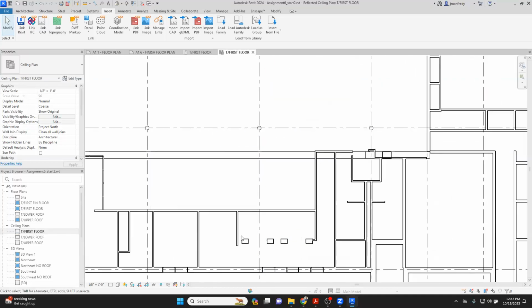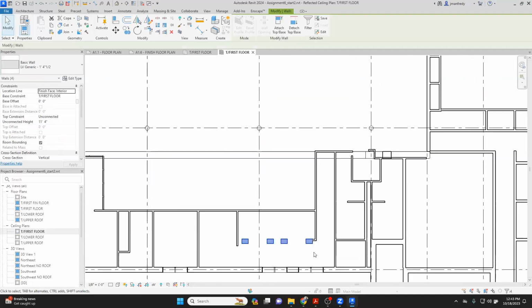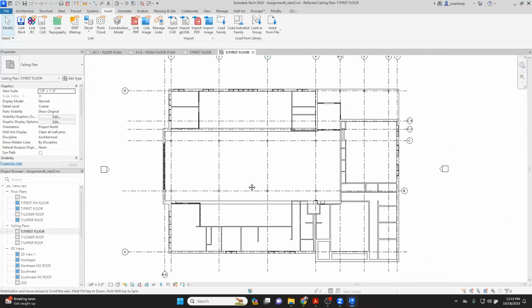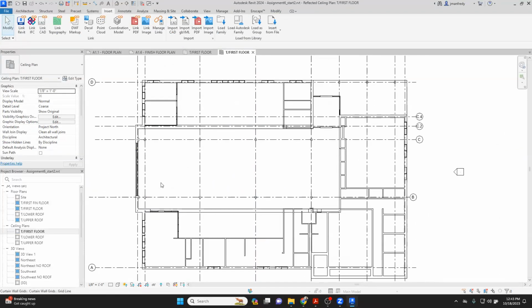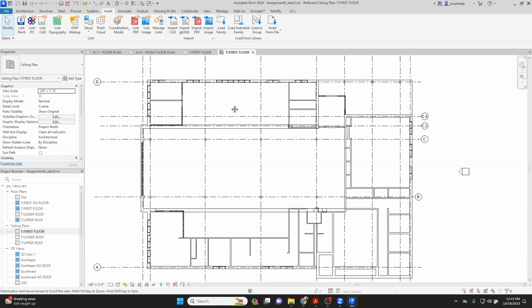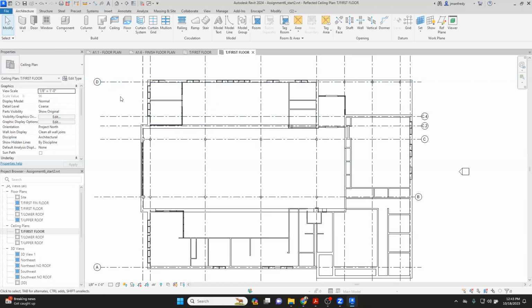You'll notice that, let me just get rid of some of this stuff here that belong here. You'll notice that on this drawing, windows appear because they must have intersected the cut line through the building. But ceilings are different than floor plans. Floor plans cut through the building at 4 feet when it creates a floor plan. Ceilings cut through the floor plan at 7'6".